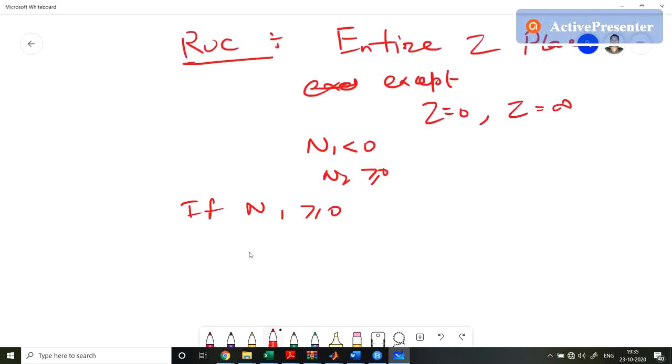So basically if we have only negative powers of z, then the ROC is the entire z plane including z equals infinity, but for z equals 0, X(z) will become unbounded, because 1 divided by z, when z tends to 0, becomes unbounded.